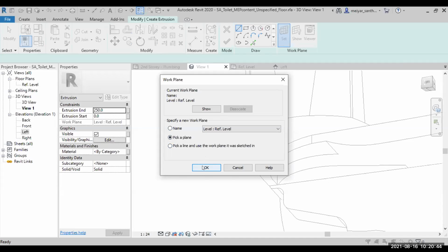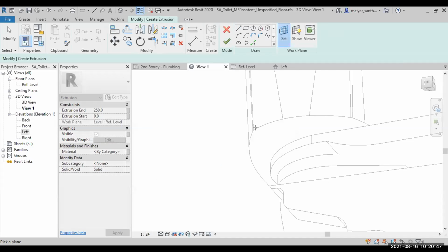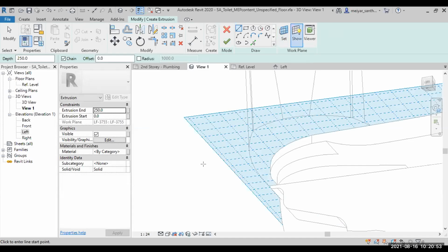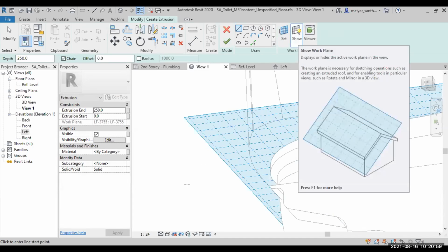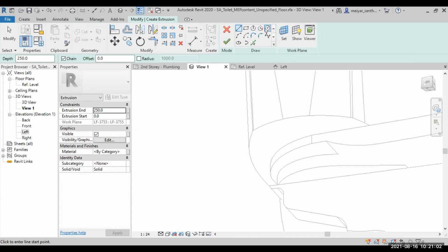Because here it never says pick a surface, right? Pick a plane now. See the plane? Select this. If you're not sure, you can show the plane with the Z, all the things that are there. So from here, no need to show anymore. Draw a circle. Okay, on this, somewhere here. So the radius is 7.5. Yeah, like this. Okay, so 7.5. Extrusion, follow them, 1.6. So at least you know that it's able to do snapping.